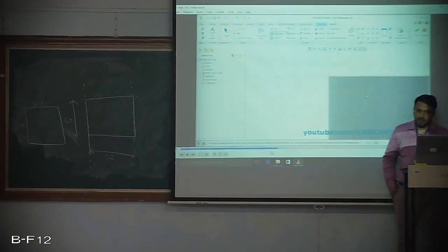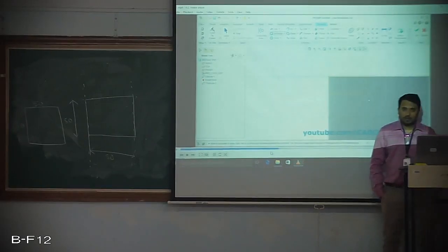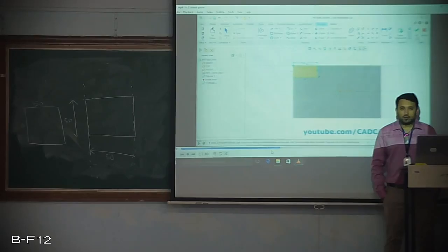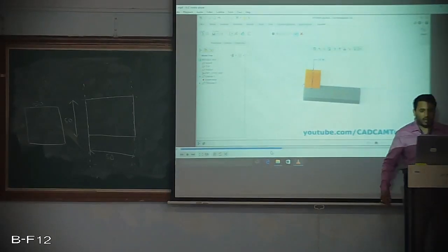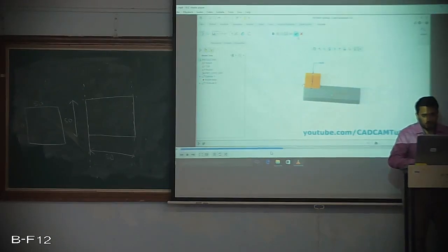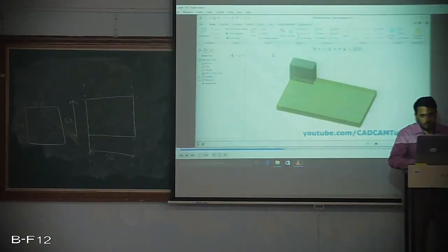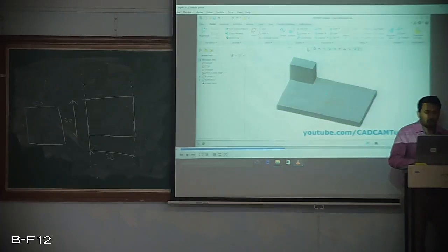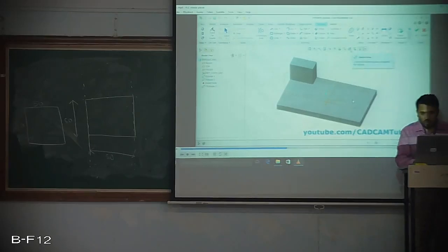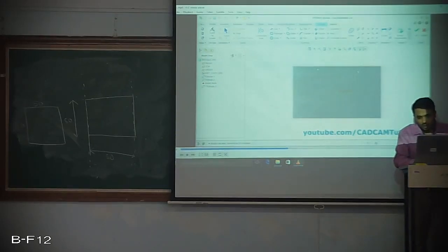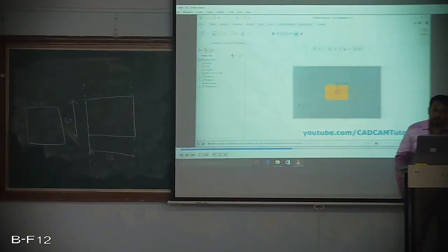I am using a rectangular command, and I click the first left corner and drag it to the bottom right corner, and if I click it and come out of the sketch command, it will extrude the part with the dimension I have chosen, and then click OK. So this is how it looks. But again, I wanted to extrude one more. So click on the surface and click on sketch. It will orient to the sketch, and all the sketch tools will be available here. And again, I am drawing one more rectangle over here. Then click OK.